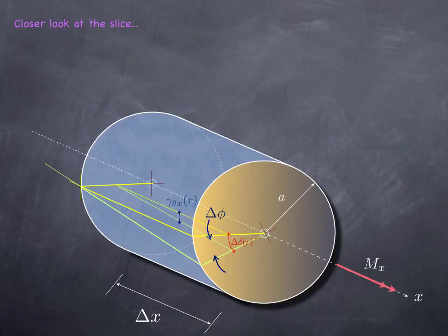So this shear strain will obviously be a maximum at the surface of the shaft where I put my original cross mark, and it will become zero at the center of the shaft. There's no shear strain in that circumference theta x direction at all.